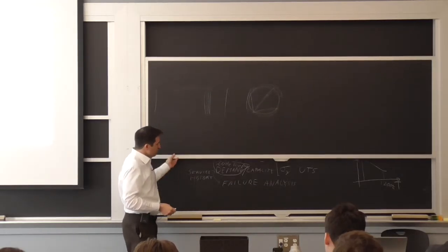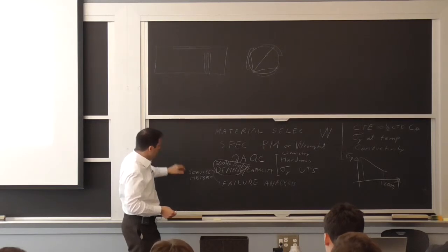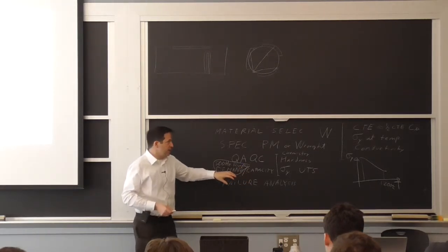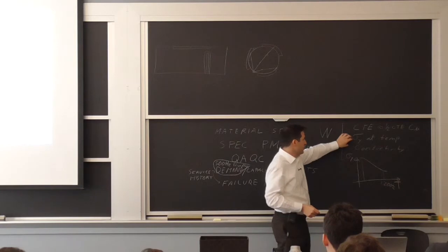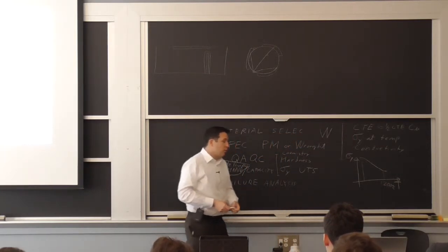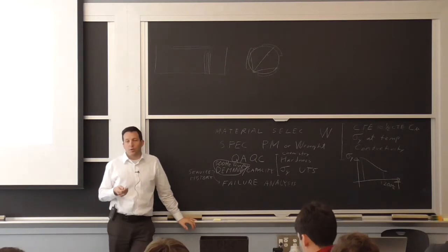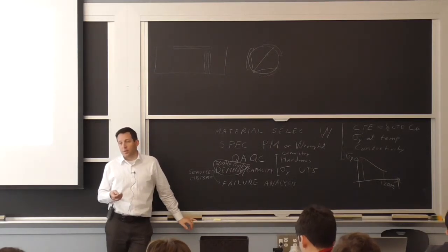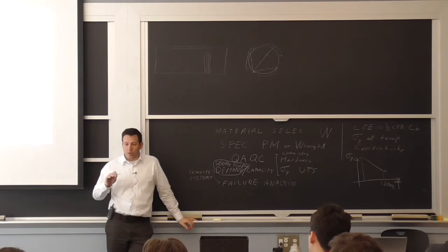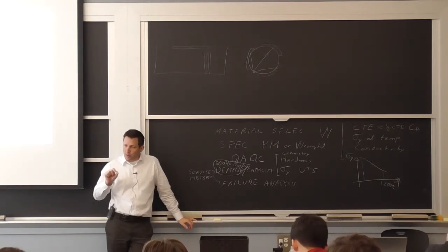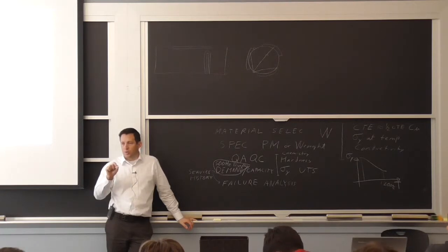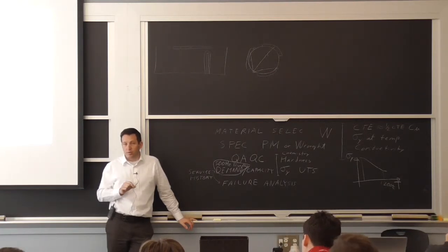So knowing that, we're back here to the demand and capacity, to what we're looking for, temperature, and what you really wanted to do is avoid having that deformation. You didn't want to stretch the tungsten alloy. If you could stay in a regime where you're close to the yield strength, but below the yield strength, you get a very long life. But as soon as you start deforming it, each cycle is where it will initiate these cracks, and now it will propagate them at 600.